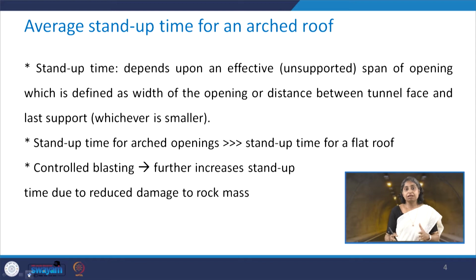But if the stand up time is low, which will happen in case of poor rock masses, then the time for the installation of the support system is extremely low, and then we have to do proper planning in order to take care of such a situation.